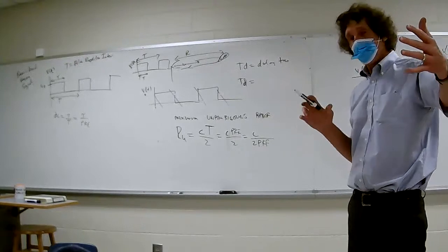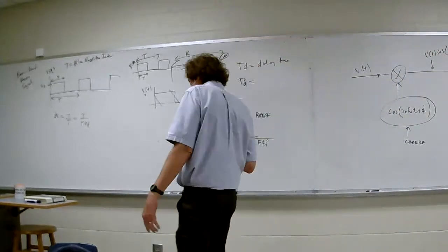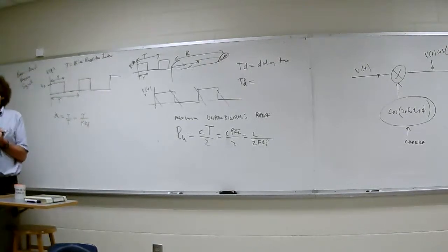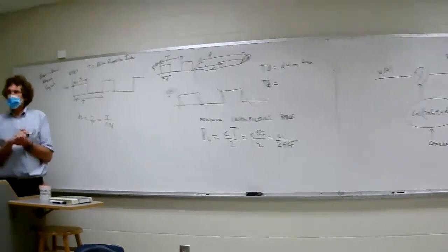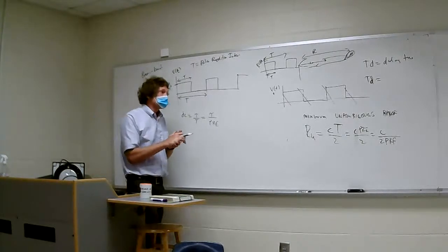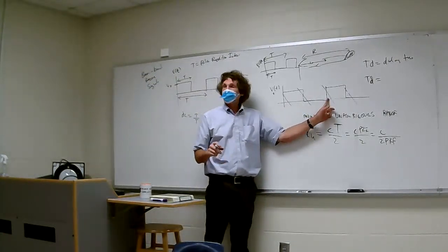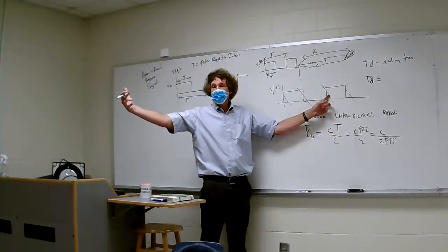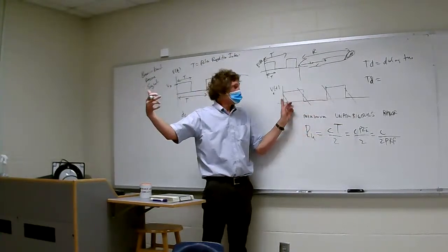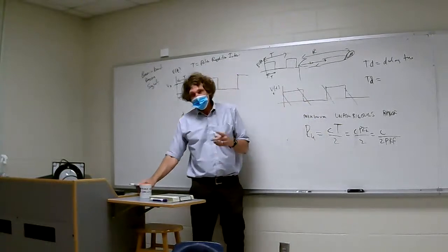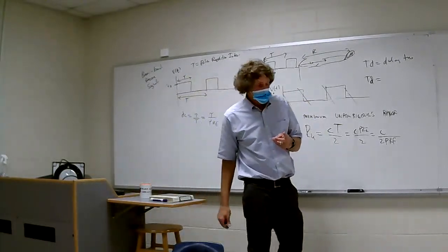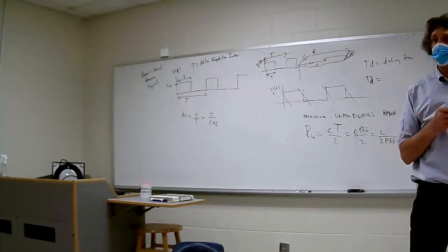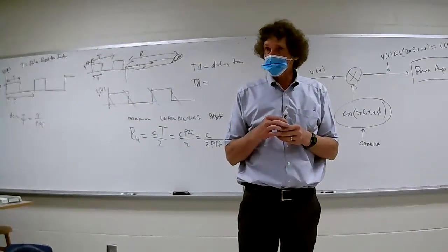So here's the deal. Usually when you're building a radar and trying to do detection, you figure out, well, what's the furthest target I care about in its size? Then I can design this pulse repetition interval. If I know the maximum range I care about for a target, then I can design this pulse repetition interval. Now the other thing is this. As I send out energy and it hits and comes back, it's falling off as 1 over r to the 4th. Y'all follow me?